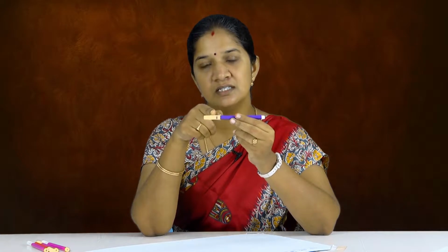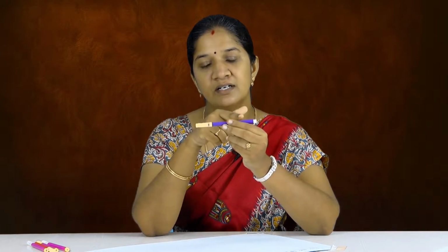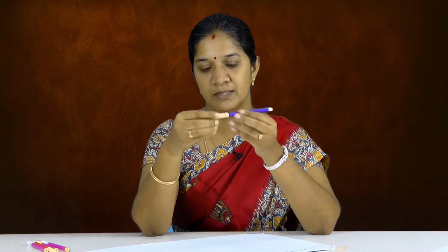Due to this variation in the bending moment, shear stress is generated all along the section. Wherever you have a difference in bending moment, you will have some shear stress variation. This shear stress variation is caused maybe due to the grade of concrete or the interlocking between the concrete elements, and the interlocking between the concrete and the steel elements. Let me clarify how shear happens in beams.